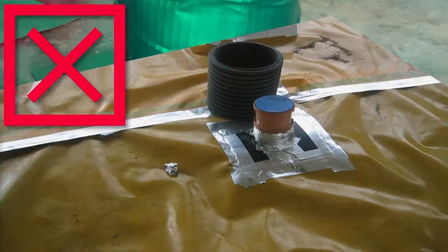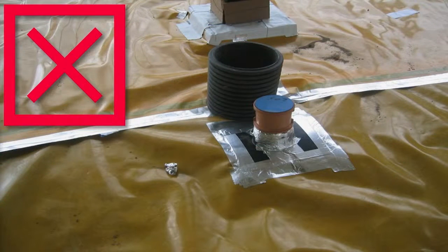In the second, the smaller pipe appears to have been relatively well sealed, but the larger is not sealed at all and corresponds to a lap in the membrane, creating additional complications. The close proximity of the pipes to each other also makes detailing and sealing using proprietary top hats difficult.